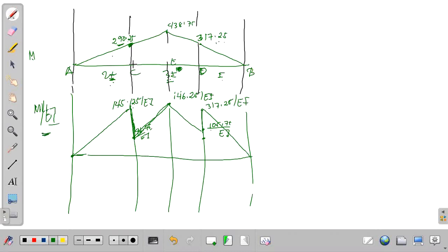Okay? Since our beam is non-prismatic, magkakaiba yung moment of inertia natin. So our moment diagram is different from our M over EI diagram. Okay? So nagets ba kung paano nakuha yung M over EI diagram? So you just need to divide the value by I para consistent na tayo na EI. Okay?